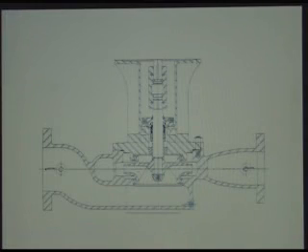Well, for a pump, you have liquid coming in and it's suddenly being accelerated through the impeller. That sudden acceleration causes a localized static pressure drop. If the static pressure drop goes below the vapor pressure of the fluid, you will end up having a vapor bubble form within the inlet to the impeller. And as the fluid moves further out the impeller and static pressure starts to go back up again, it will then collapse.